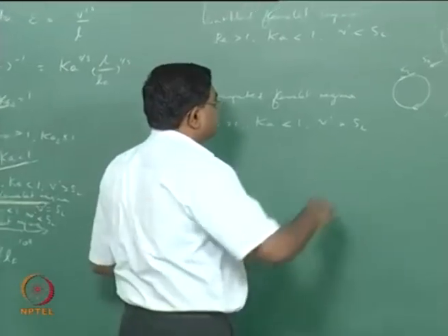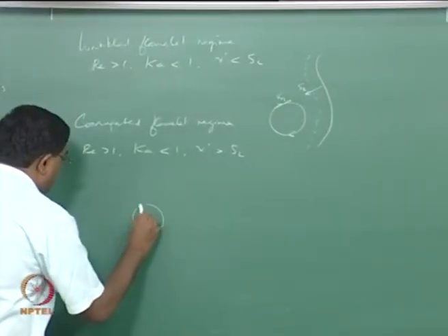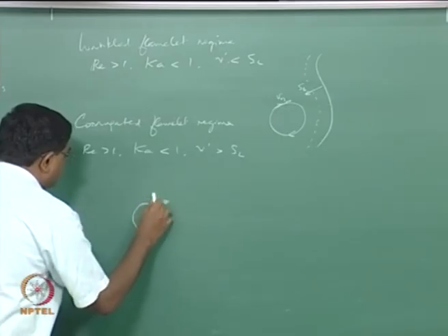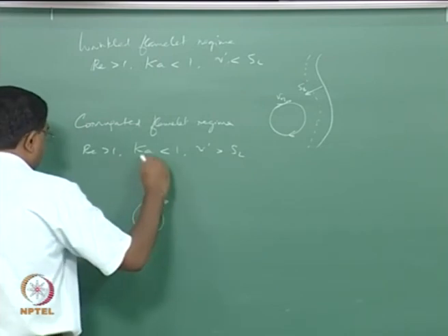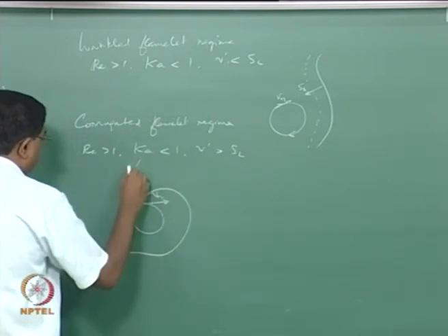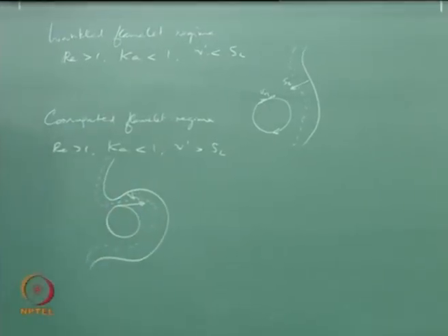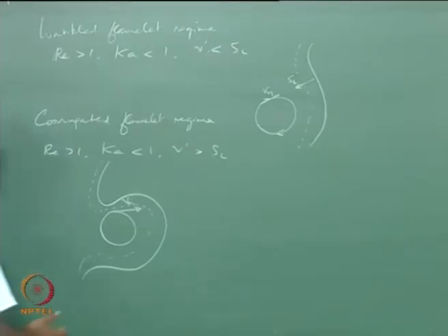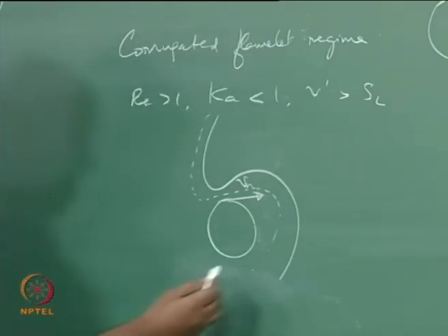So what happens when this begins to increase? If you think about an eddy that now has a larger Vn, and a flame interacting with it, the flame actually begins to curl up to encompass that. You could exaggerate this a little bit more.